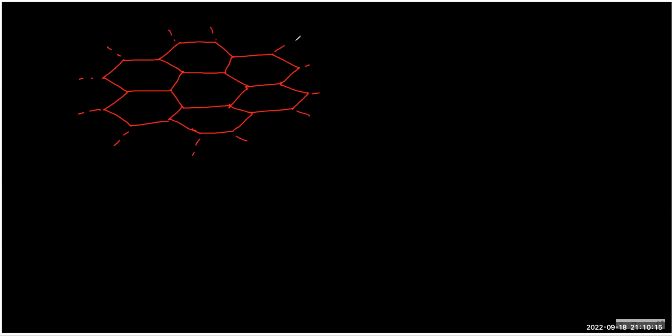And what you can see at any junction now, it will be Q by 3. 3 branches, right? So if I choose here, then this branch will become 2Q by 3. And therefore the equivalent C we will get is 3C by 2. That's why I said NC by 2. What is N here? Number of branches. You can see there are 3 branches. So 3C by 2. Earlier it was 4C by 2, and the answer was 2C. Understood?